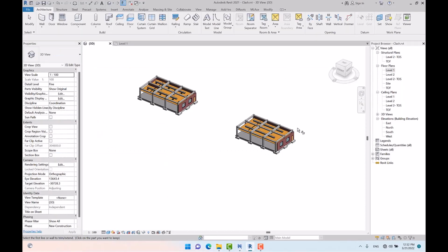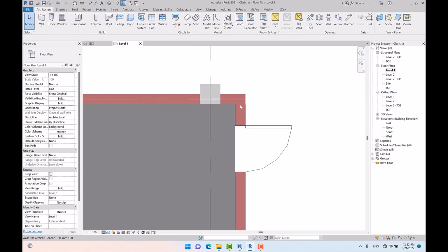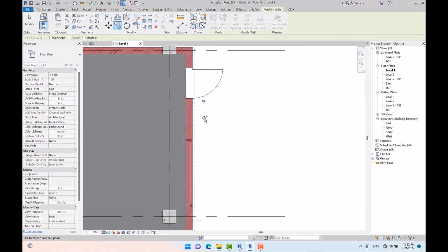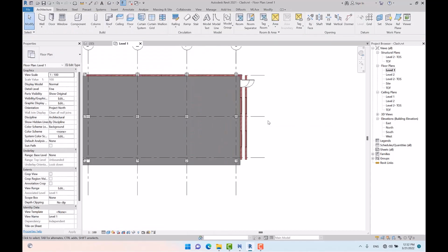Here in Revit, check this out. I'm going to give you the last example for the duplicate. Then I've got a question for you. Here I copy the wall, and after that paste it here, and as you can see, there is a 1 meter offset between them. Suppose that here we have 2 walls, for example. In other words, we have a 2-layer wall. So just let us check this out.